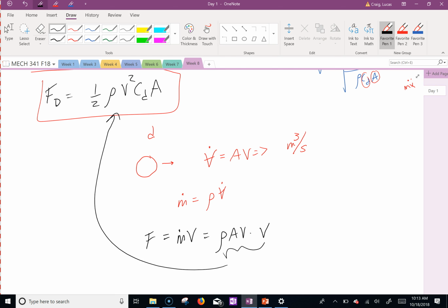And the idea comes from a cannonball and understanding, okay, it has got to somehow displace that much volume per time. And we know from that standard force that's kind of that. All right? So this is kind of briefly where that 1/2 rho v squared CD A comes from. Okay, it's kind of cool. It's right in the stuff you've been doing. You just didn't realize that.